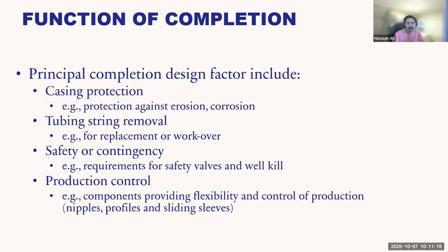So you want to have the flexibility of killing the well to protect the environment and protect against any blowout or uncontrolled exposure of well fluid to the surface. And then production control. You want to have flexibility in selection of your components so that you can control your production.